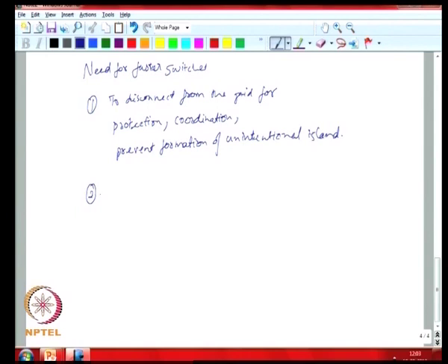So, if your grid power quality is poor for some reason, and your switching speed is slow, it means that your load is now exposed to that poor power quality for a longer duration.